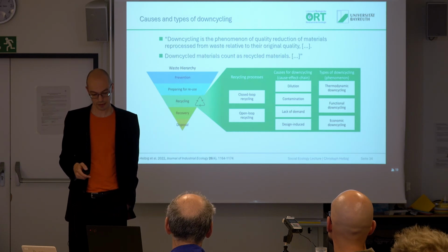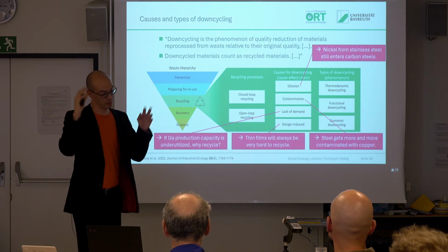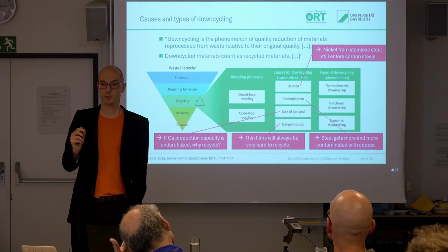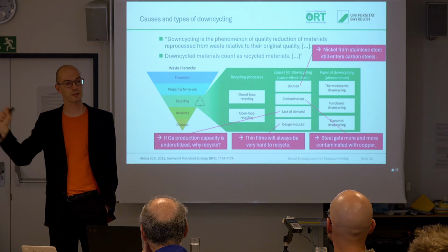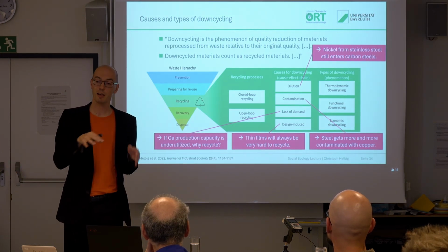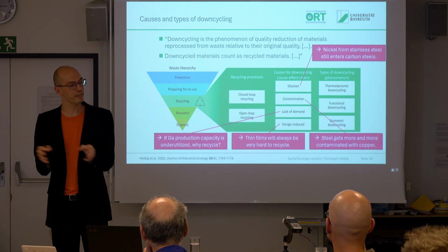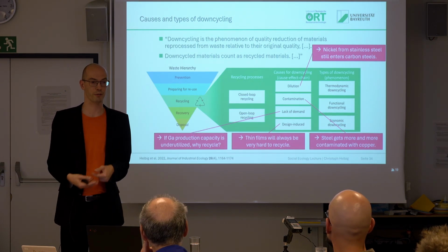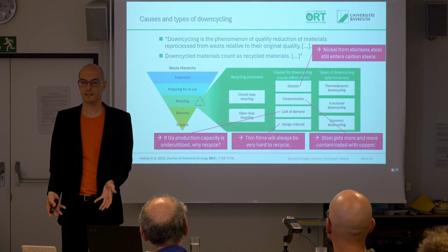A few examples. So we already talked about nickel a little bit, which is a strategic raw material. For nickel recycling, the main issue is that nickel sometimes gets diluted into carbon steel. We use it mostly for stainless steel, and also for batteries nowadays. And some parts of the stainless steel always get collected with carbon steels together, and then it's recycled as carbon steel, and then nickel is basically just a filler material in carbon steels, where it doesn't make any sense to have it there.